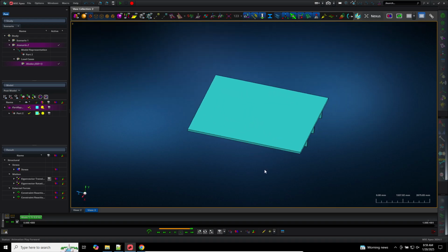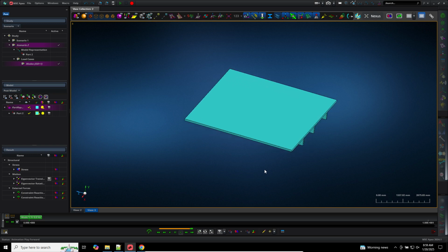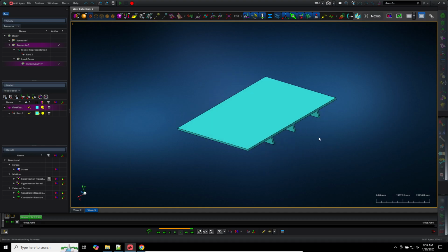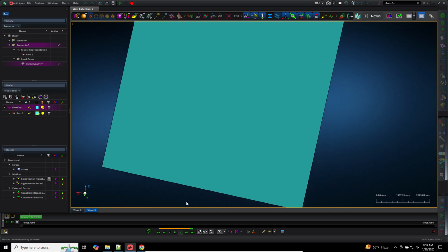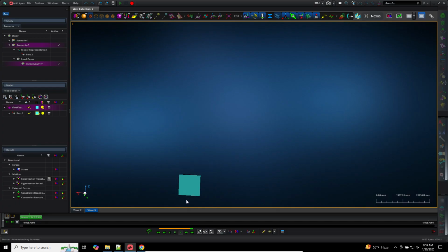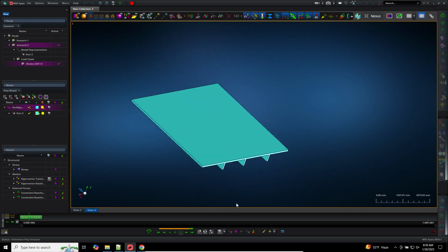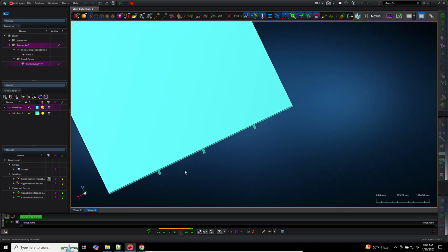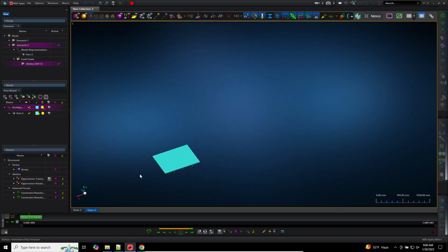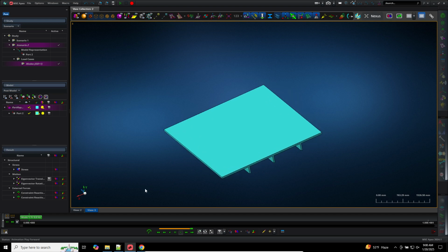So it's up to you to look at the mode shape that we get at the end and ask yourself, okay, this is telling me which direction is not constrained. And right now it's telling me it's allowed to rotate about the y-axis. What's going on here? This makes sense. We don't have constraint along the z-axis. So this model can either translate along the z-axis or it can rotate about the y-axis. So this is a way to detect which direction is not properly constrained.